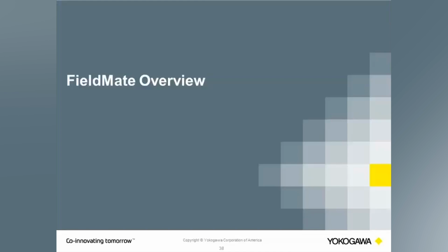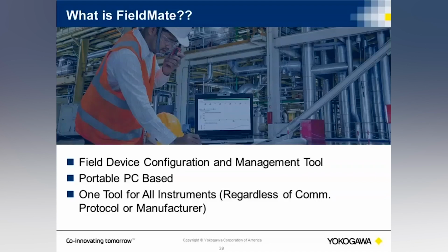The next Yokogawa tool I'll go over is FieldMate. FieldMate is kind of the glue in the whole process. FieldMate is a device configuration and management tool. It can be portable or operated via PC. It's essentially a management tool to connect to various types of field instrumentation, whether it be pressure transmitters, flow meters, or temperature transmitters. It supports various protocols that are commonly used in the field, and it also allows you to connect to non-Yokogawa devices as well through the open DTM FDT framework.